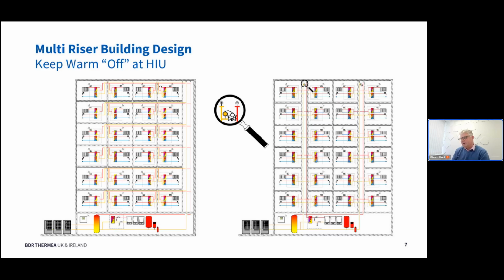Here you can see a typical communal heating system with some hybrid heating, with air source heat pumps typically delivering 85% or so of the annual load, and maybe some peak load boilers delivering the remaining load on the coldest day. We find this hybrid approach really reduces the capex and also the DNO electrical capacity you need off the grid.